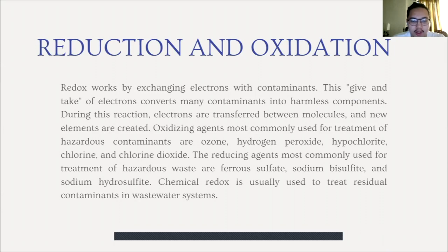The common oxidizing compounds used for treatment are ozone, hydrogen peroxide, hypochlorite, chlorine, and chlorine dioxide. And then the common reducing compounds used are ferrous sulfate, sodium bisulfite, and sodium hydrosulfite. Redox is usually used in treating contaminants that are in wastewater systems.